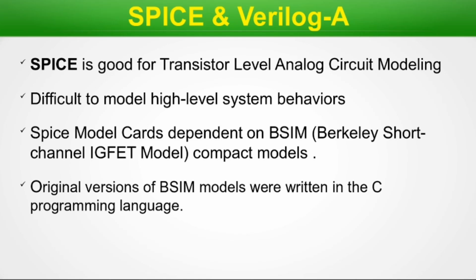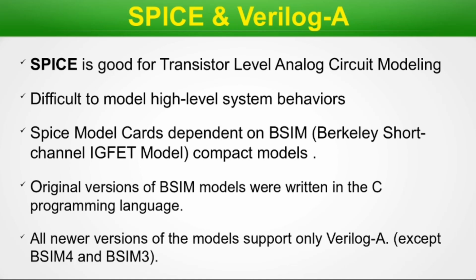Now let's come to an interesting point here where Verilog-A comes into the picture, which joins SPICE and Verilog-A. All new versions of the model support only Verilog-A. I am talking about the BSIM models, except BSIM4 and BSIM3. Now let's see which are the latest BSIM models.